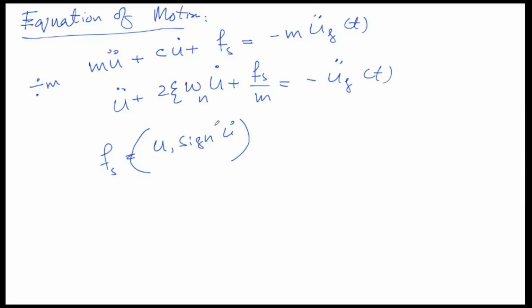As for the linearly elastic system, numerical methods for solving this equation are implemented in a number of computer programs, and we already talked about this in the past lectures. But in case of the inelastic behavior, special attention must be given to the numerical procedure to detect accurately enough the time instant when the system transitions from an elastic to a yielding branch or vice versa.